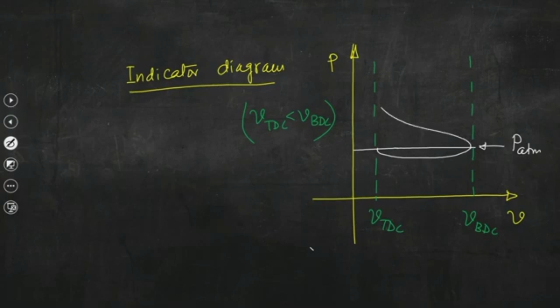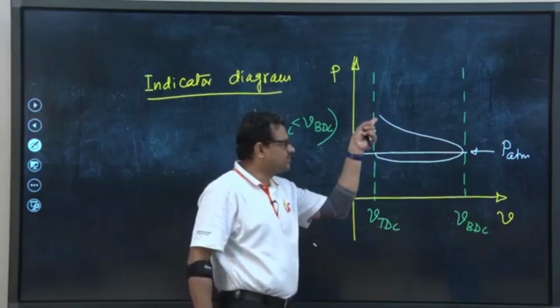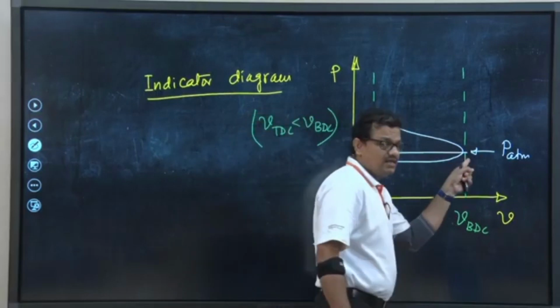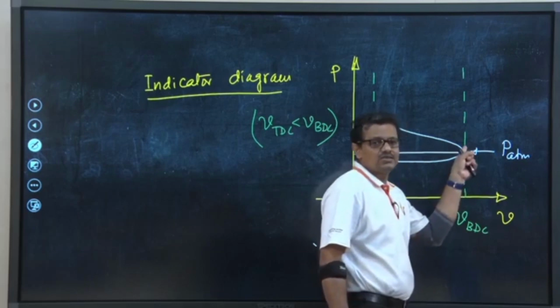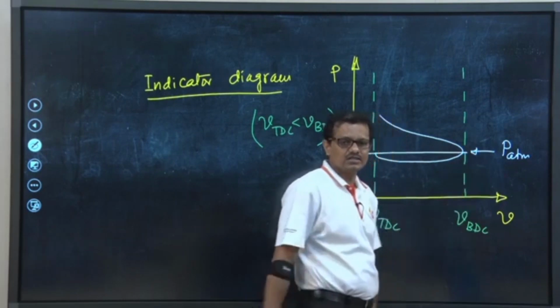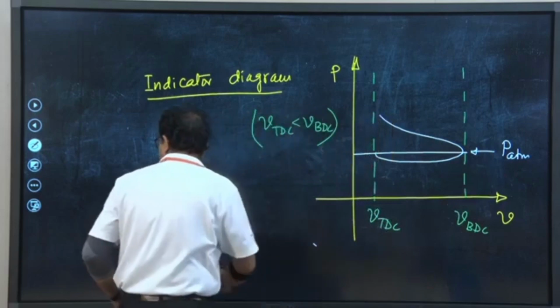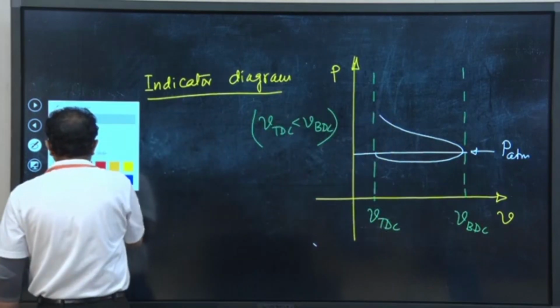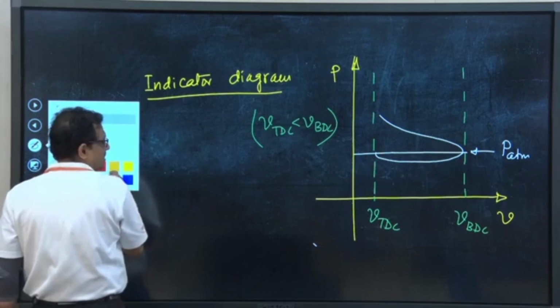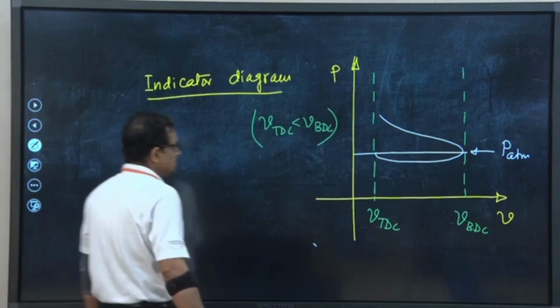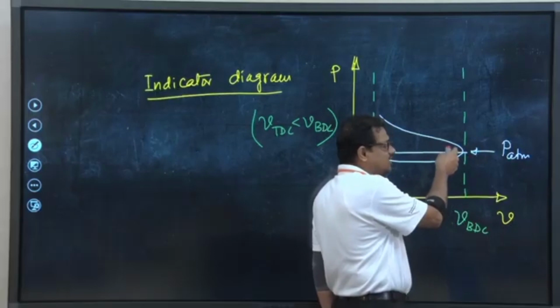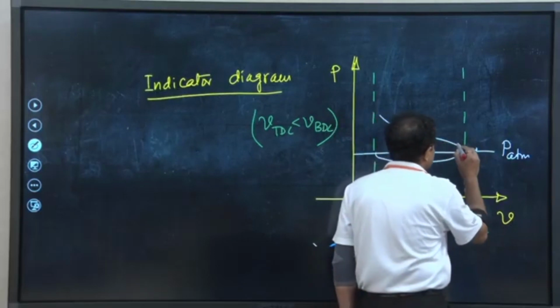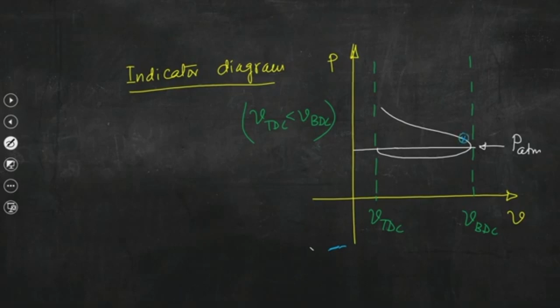Okay. So, volume is getting reduced, pressure is increasing, and that is the object. Now, ideally we should close the intake valve when piston is at BDC, but it is not the case. We shall discuss all these things later. So, what is done? If I mark here, it is not exactly at BDC, but slightly when the piston is slightly away from BDC during the compression stroke, here this is the point.